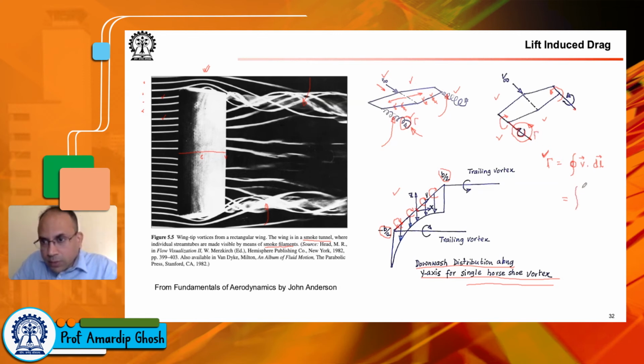In terms of your vorticity, it can actually be shown that if eta is my vorticity, then circulation is essentially the vorticity multiplied by the surface over which it acts. So if you think of a cross section such as this, you have to multiply the vorticity by the cross section over which that vorticity acts. And of course, you take the component of surface, so if your vorticity vectors are normal to the surface, then you just take the magnitude and multiply by the area. Of course, if they have some mutual inclination, not aligned at 0 degrees to each other, then you have to take the component properly.